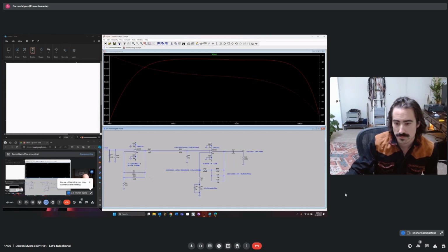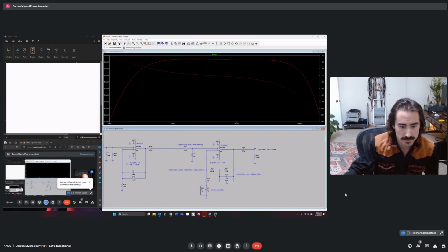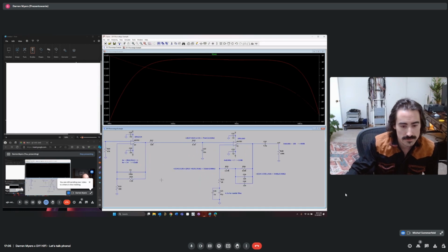Yeah, and why is the R21 dominating? Because you would think that it's the R22, which has a higher thermal noise. So why is it the 21? In order to see that, we need to imagine that you were able to look into the impedance from this perspective.